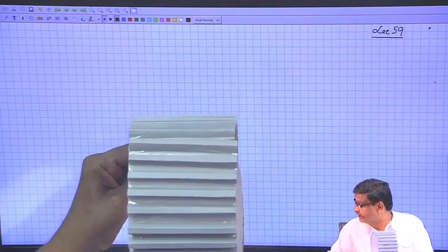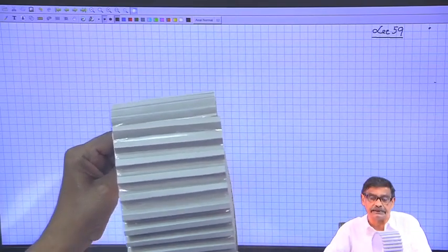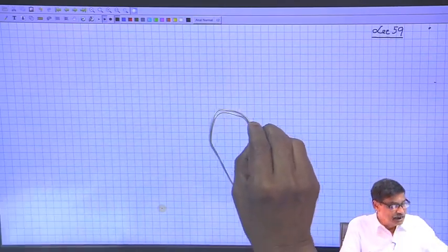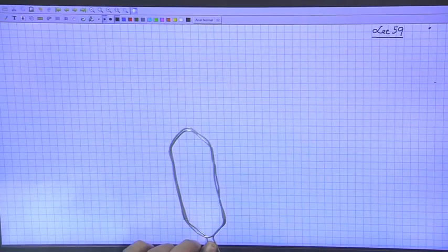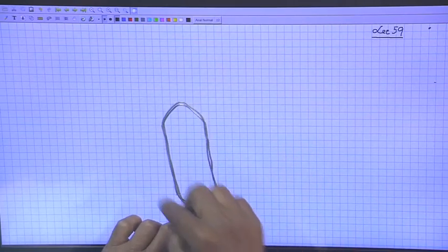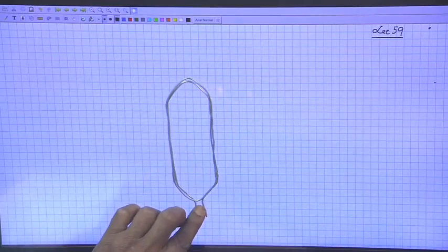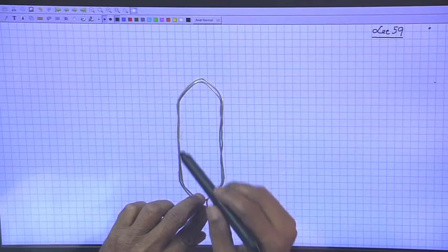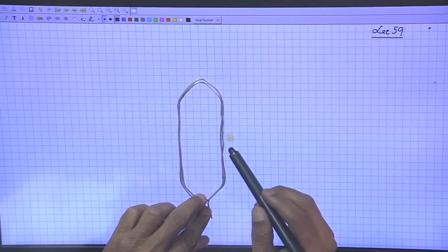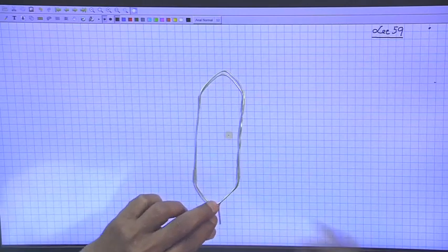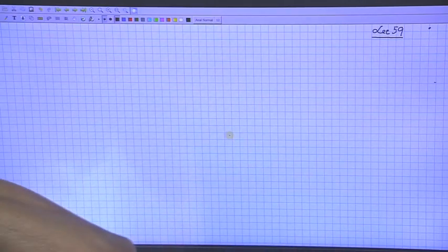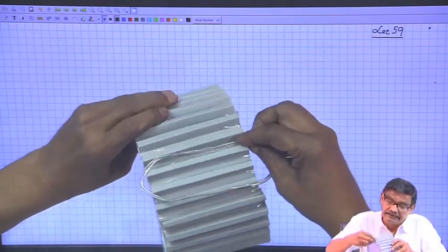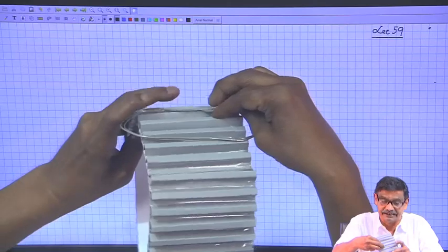But the armature winding is rather interesting. So, this is a coil, which is diamond shaped like this. It is a coil like this, and this coil has 2 coil sides. If at any time this coil side is under a north pole, the other will be under a south pole. So, how will this coil be placed? It will be placed in its designated slot like this here.